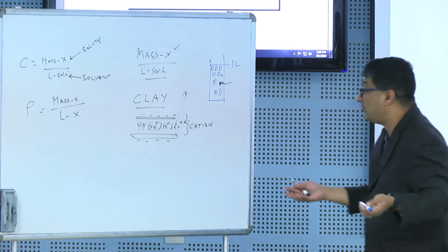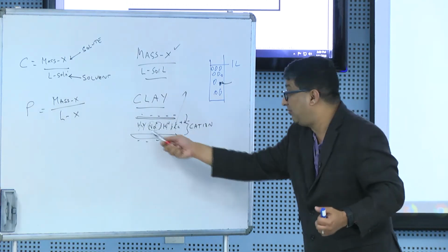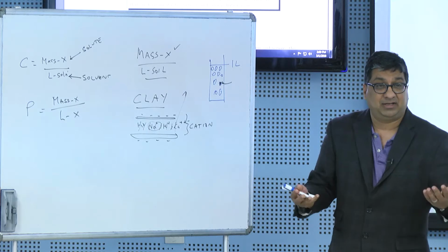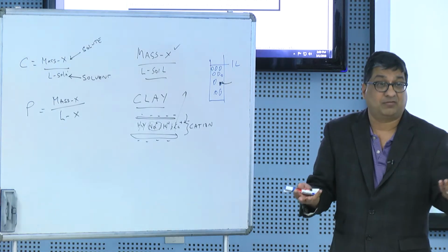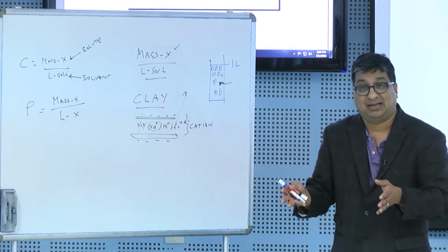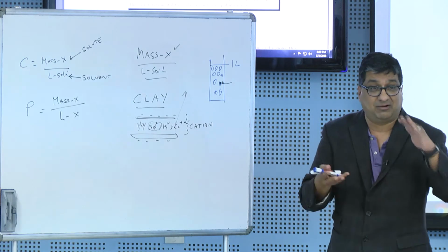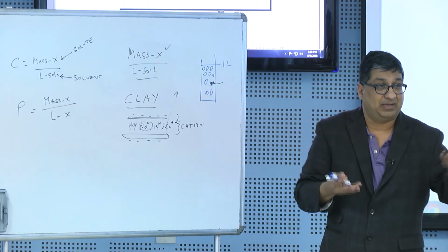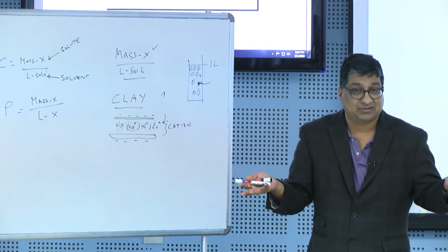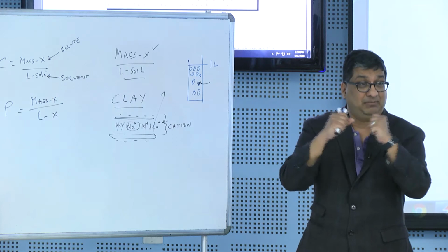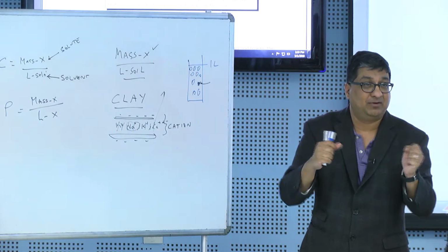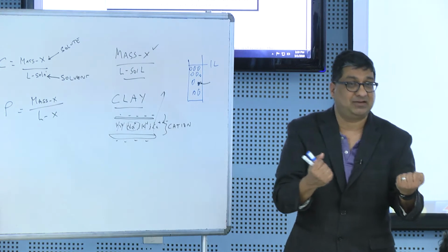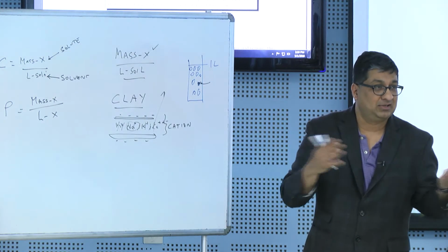For our discussion of concentration, the amount of water that's in there will define the volume, and that can vary in soils. In aquifers, you're fully saturated with water, but in soils like the vadose zone, the upper portions, you have air and water in your system, so your density changes based on how much water is there, because the air doesn't add to the mass. But nonetheless, that air and water keep the particles in a certain arrangement. If I remove that water, my arrangement changes, and so will my volume. My mass will not change significantly because I'm not removing the solids where most of the mass is.